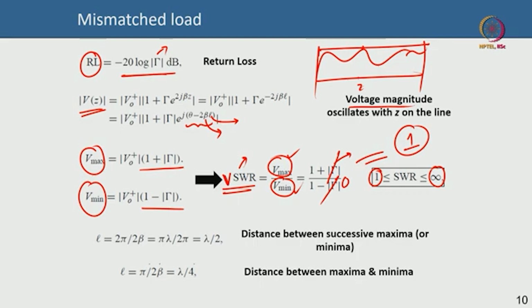Infinity is the most horrible value, a crazy situation. You do not want the VSWR to be very high. In other words, when you test the ruggedness of an RF transistor, if you recall from our long-back discussion on LDMOS and gallium nitride transistors, ruggedness is the ability of the RF transistor to experience voltage excursions and still work fine. So, that is related to VSWR.